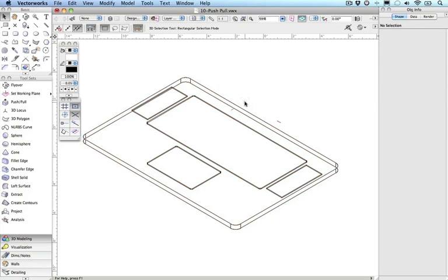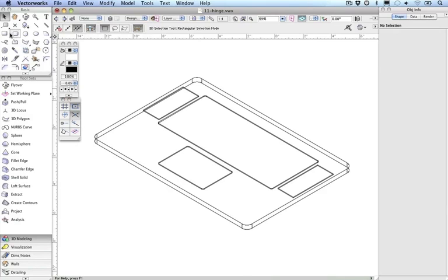Now we'll cut out a space for the display hinge. Select the Rectangle tool from the basic palette. Then select the third mode, Side, Center, and Opposite Corner Rectangle mode. Choose Automatic from the Layer Plane drop-down menu in the view bar.